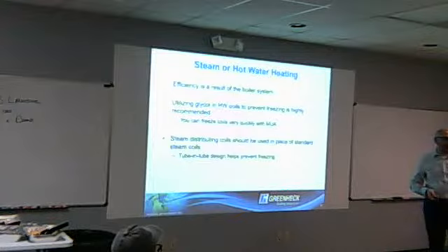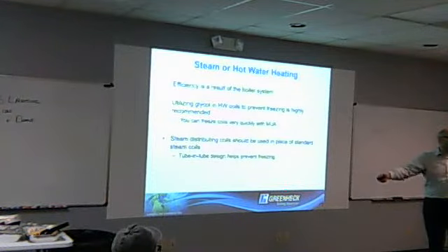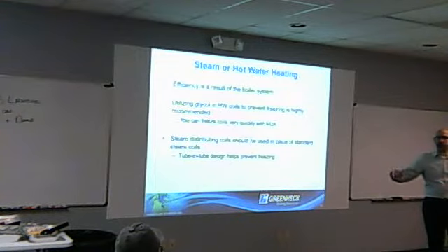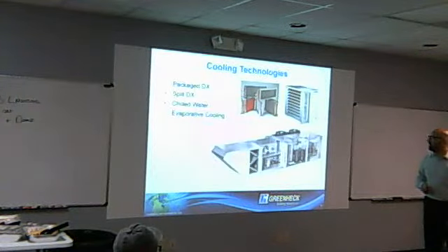We say if you're going to go this route, you've got to have provisions in place, like shut down the unit if you have no heat and the temperature is below, like, 45. Obviously, it's not going to freeze at 45, but give yourself some safety factor. Don't wait till it gets to like, hey, it's 5, let's shut the unit off. Too late. Yeah.